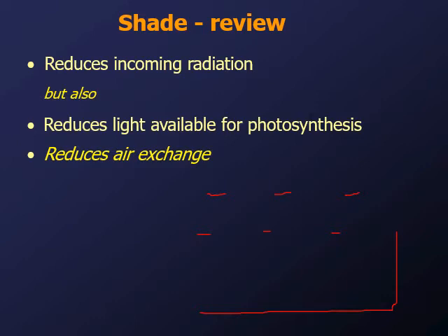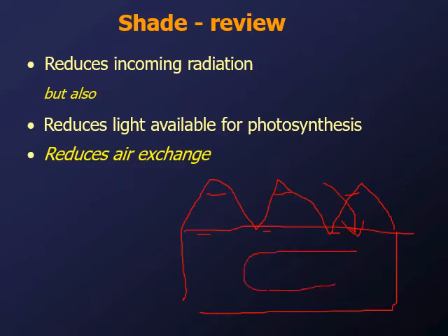So generally speaking, in temperate climates, the shade is inside the greenhouse. Which of course means that there's less opportunity for air to move into the greenhouse proper because it's covered, right? You can't get fresh air getting through. So we reduce our air exchanges. That has implications for humidity management and things like that.